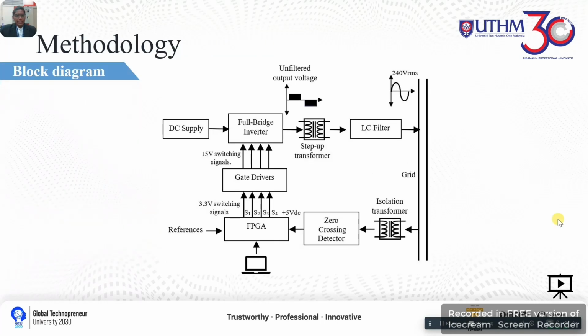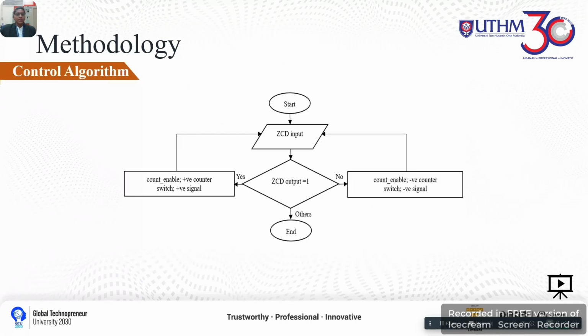In this proposed system, the key components were a single phase full bridge inverter, a ZCD, gate driver units, an FPGA as the controller, LC filter circuitry, and also two types of transformers, which are an isolation transformer and a step transformer. The design algorithm flowchart for producing the synchronized signal based on ZCD integrated PLL is as shown.